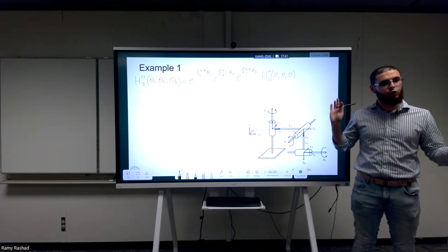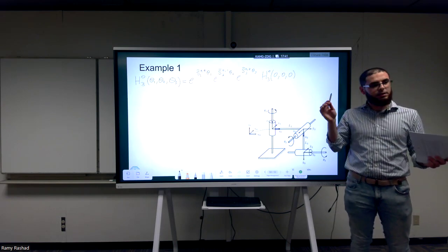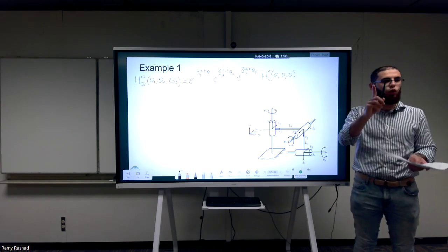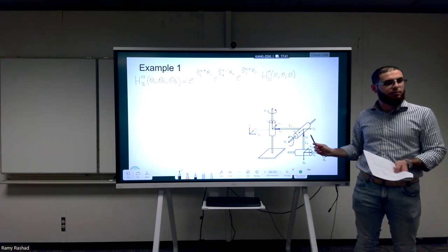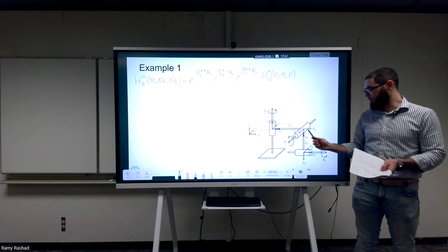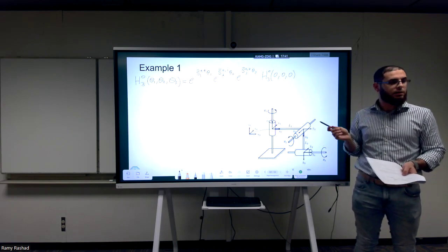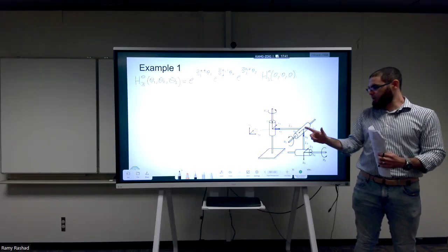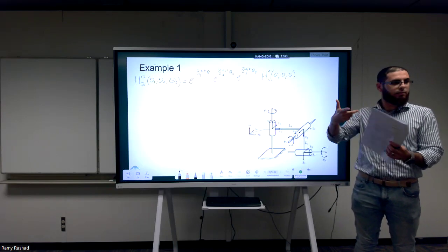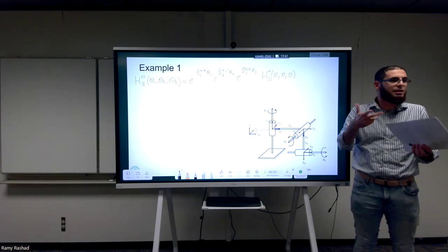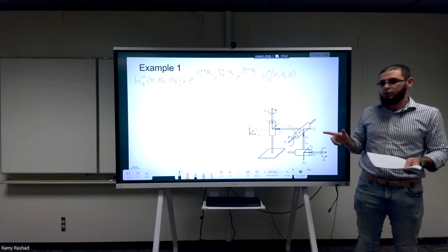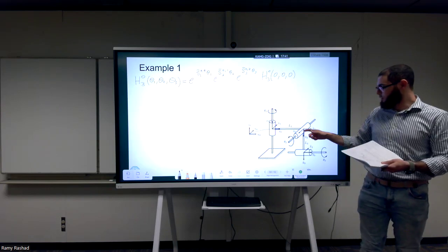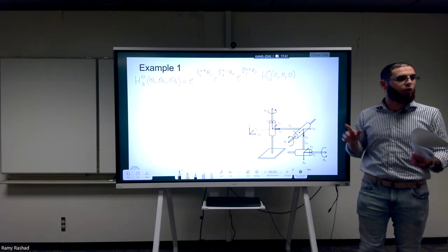Orientation is completely your call. It makes sense because the calculations we're going to be doing are to align at least, only one, of the axes of the coordinate frame with the joint axis. You can, of course, in general, choose frame number 2 to be a funny orientation. And this, again, will be an axis that has components in X and Y and Z, but again, you're just making your life hard. So we always put the frames aligned with the joint axis. Should I choose this one to be X or Y or Z? It's your call. It doesn't change anything.